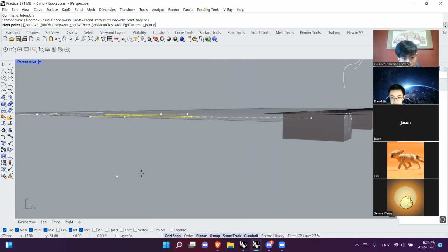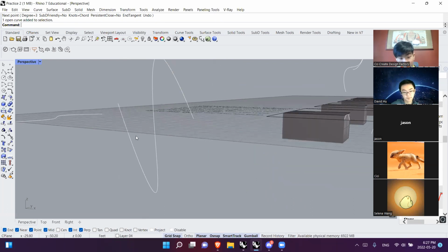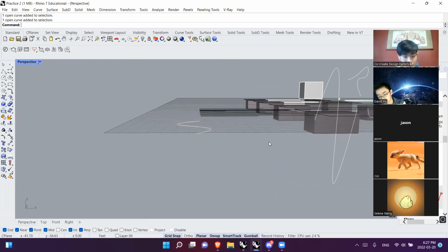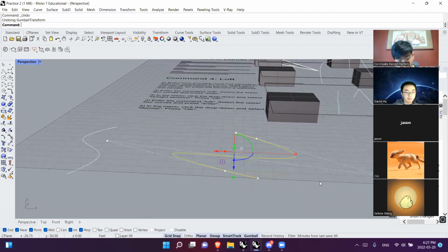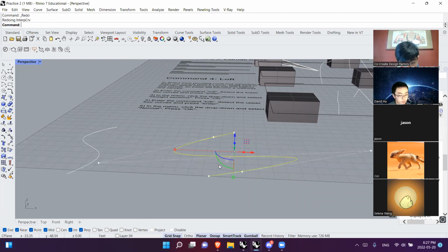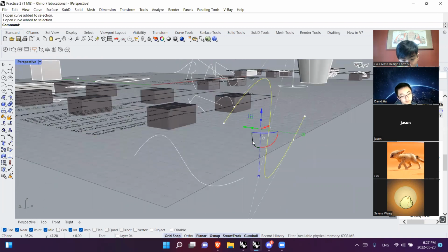Or another way to do it is, if you left click onto this arc here, you can actually type 90. So let's type 90. And yeah, it makes a rotation based on the value you put. So if you want to do 180, the shape is just going to flip 180 degrees, but we want 90. So, 90. This one also as well. And when you hover over the right arc, it's going to turn black. So 90 like that. And I think this should work. Actually, I should turn this 180 because,